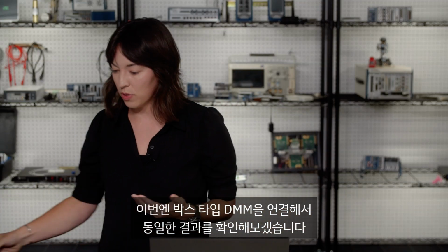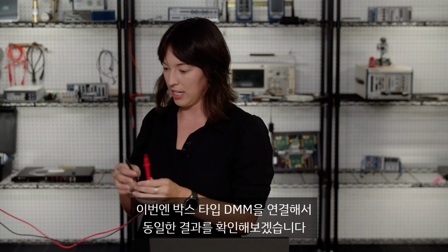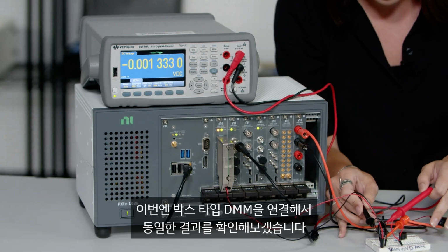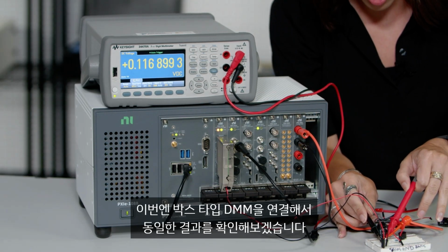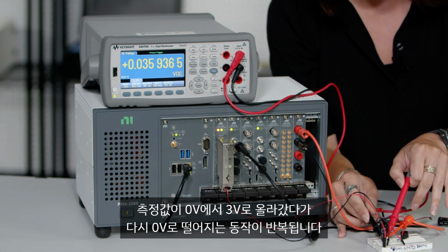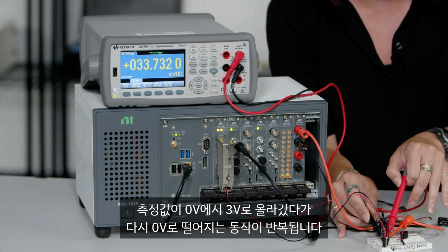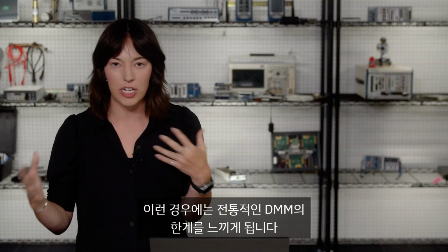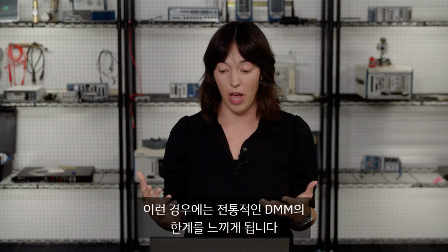Just for this one too, I'll show if we connect this box DMM, we're going to see that exact same behavior on the box DMM. You should see those numbers gradually going from 0 to about 3 volts, back to 0, back to about 3. Typically this is where you reach the limitations of typical DMMs.